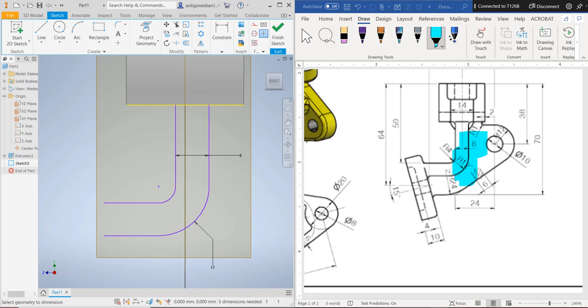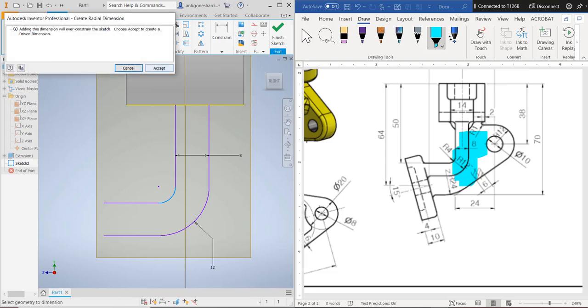Vice versa, if the inside radius is whatever, the outside radius is whatever plus the thickness of the material. Put that in your notes. It's a good thing to know. It's a very useful thing. So because I know that, that is why I know the inside radius is 4.